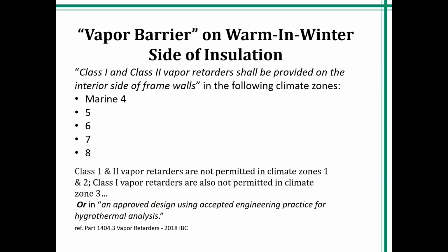Again, it's never a question of if walls get wet. They're going to get wet through drive mechanisms based on seasonal heating or cooling. Again, water vapor is always seeking its equilibrium, going from areas of high vapor pressure to lower vapor pressure. And if we have an entrapment condition, never a good situation.